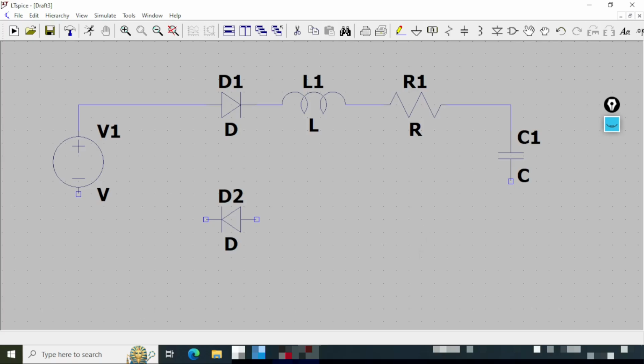Now I'll do the next wiring. Go here, click the wire. Now I here click in capacitance, and I align the crosshair at this point. Make a click to make a bend of this connection. Come here, I connect it. All these clicks are single clicks, not double clicks. So again I do a click, then come here and I align the crosshair. You can see the crosshair is aligned to the vertical grids. Now here I do a click. From this point I do a single click. And now, just to get rid of any tools, I hit the escape.